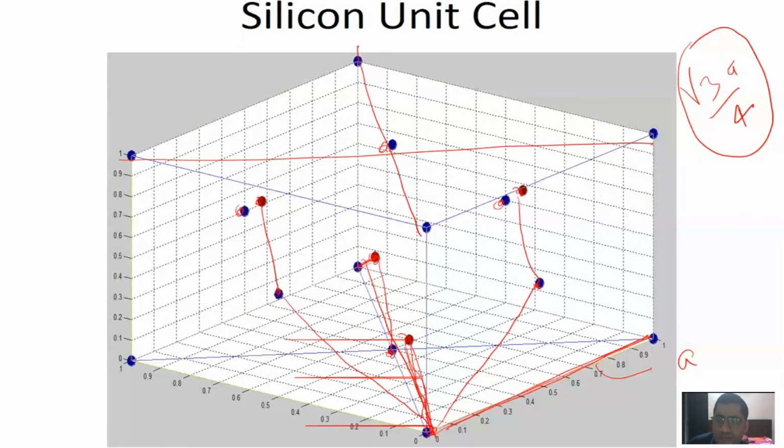Now, on what factors does the critical thickness depend? I think I have already discussed that. Critical thickness is a concept when there are two lattices or two crystals, and their lattice constants are different. So let's say this is one layer, this is the second layer. If the interatomic distance is the same in the layer and the substrate, there will be no strain.